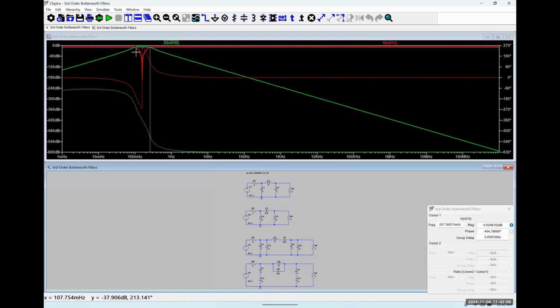So we have the exact same situation. Now the center of our stop band is at omega naught, and we once again have a bandwidth. So the width of our stop band is also omega naught, okay? So let's talk about how we are going to fix that. And that's going to be what's called bandwidth scaling, okay?